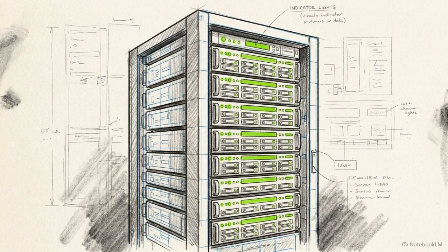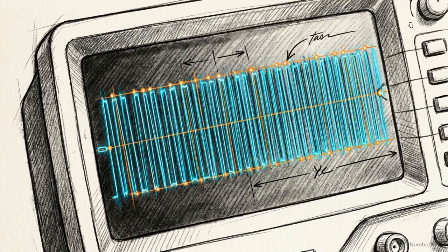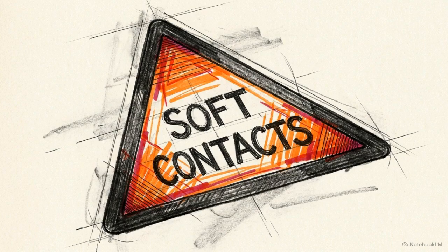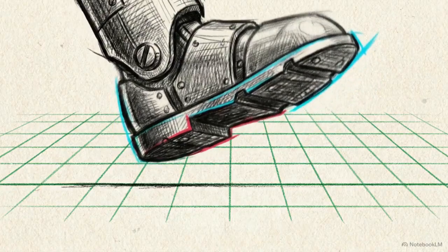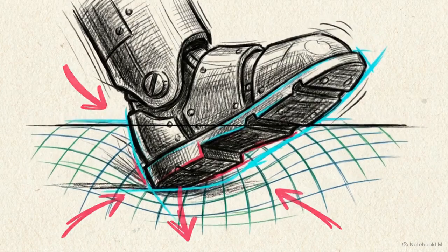Conversely, a 10 kHz time step provides excessive detail that grinds reinforcement learning pipelines to a halt with zero hardware benefit, as most servos only respond at 50 Hz. A 1 millisecond step size, or 1 kilohertz, allows you to capture contact forces 20 times finer than the actual leg movement without wasting computational power. Accuracy also depends on avoiding forgiving physics settings, specifically constraint force mixing, or CFM. Any value above 0 creates a soft physical boundary. Soft constraints allow the foot to intersect the floor mesh. Over a 30-second walk cycle, this creates an unexplained drift where the robot slowly sinks.